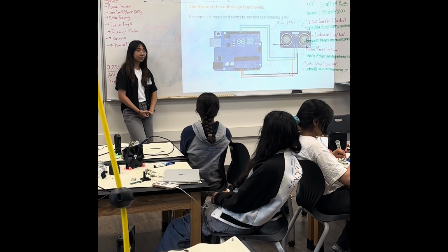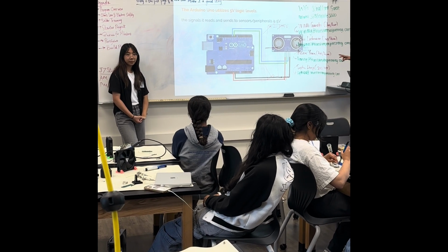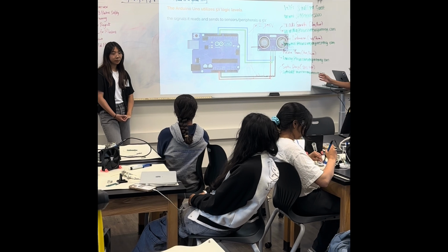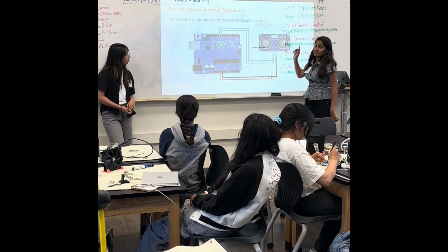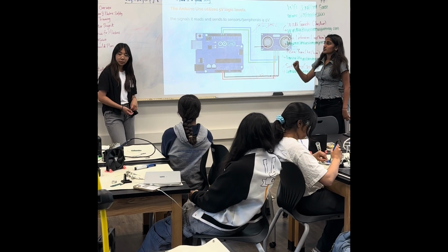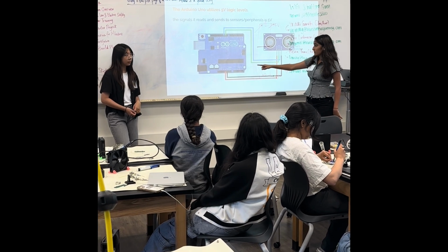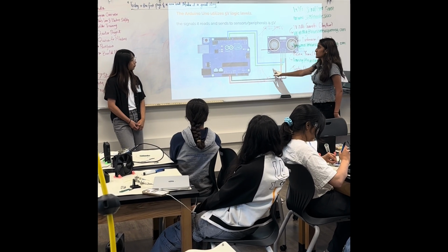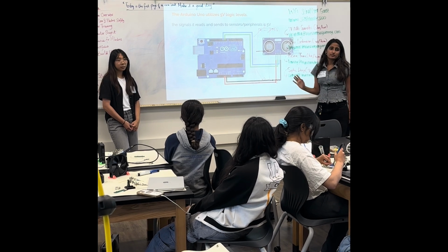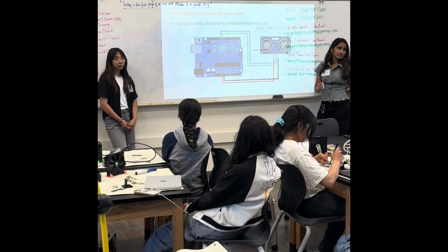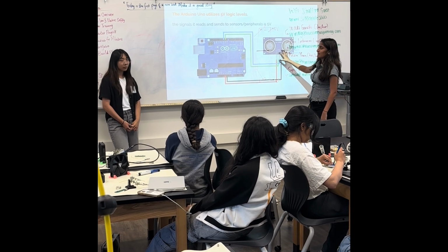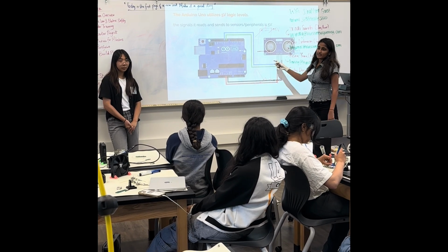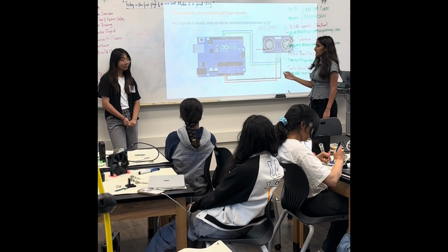Okay, so this sensor is an ultrasonic sensor which senses distance. This is a regular Arduino board. This sensor utilizes 5 volt and 0 volt logic levels. And so does the Arduino. So can I connect these pins to the Arduino? No problem. If this uses the same logic levels as this, can I connect the two? Yes, right? I can.